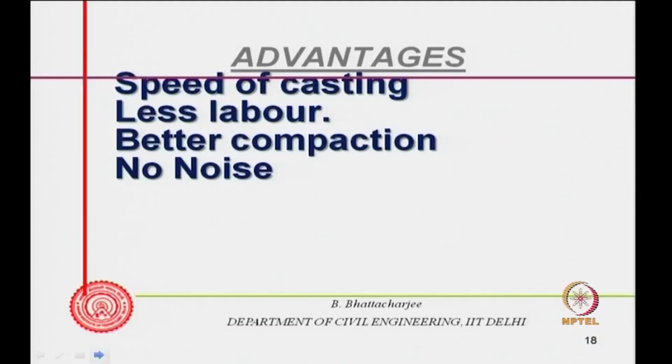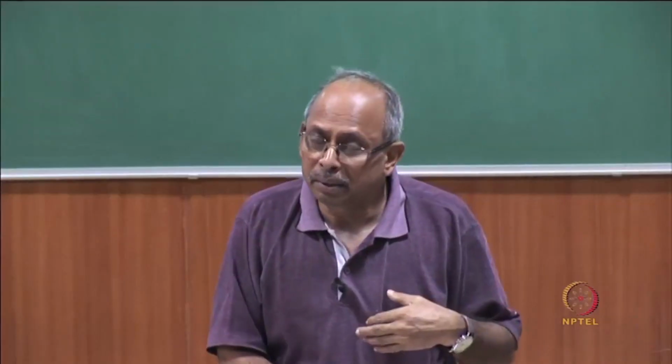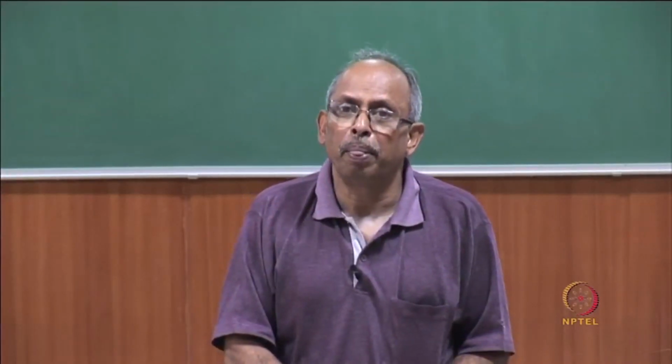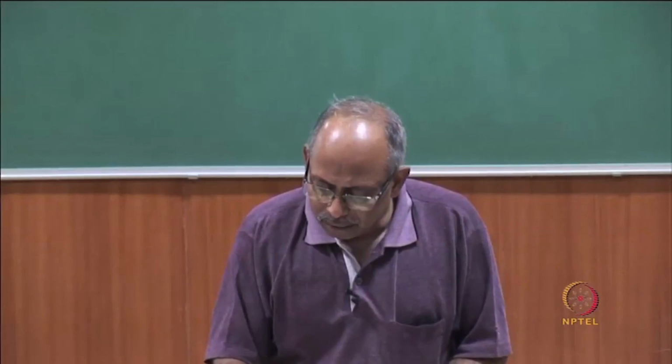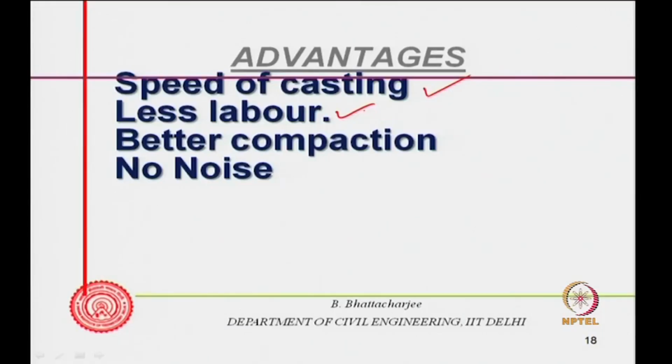So, what are the advantages? The advantages obviously, first is speed of casting. If it is self compacting, you do not require vibration, and the speed of casting will increase. Less labor, that of course is an advantage in western countries, because as I told you, it first came for these two purposes, no noise and less labor, cutting down the labor cost of vibration.